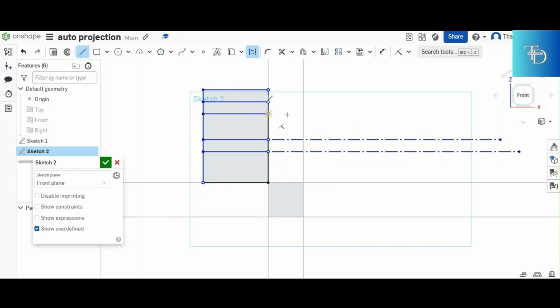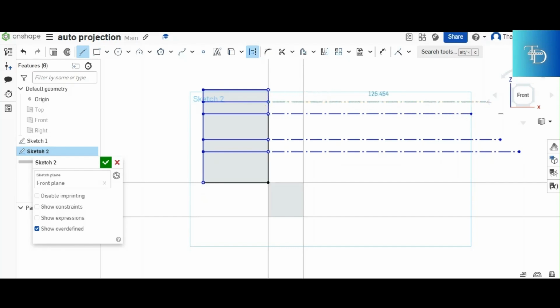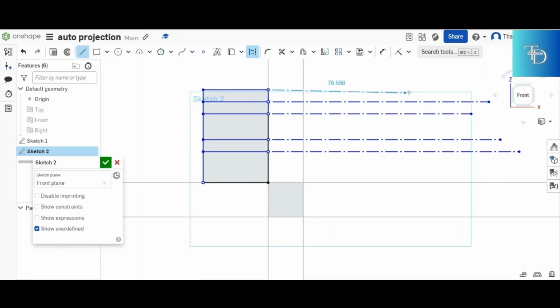You're going to have that point over there. You project that point also horizontally. Each and every dimension you marked when you were producing your front view, you have to draw to where you are supposed to place your left view. So now you are done transferring all the points except for the bottom part. That bottom corner is already there. You already have that faint line of yours. These are the newly created faint lines, because everything that you do for the construction should be in faint line. The only thing you outline, remember, is the final product.